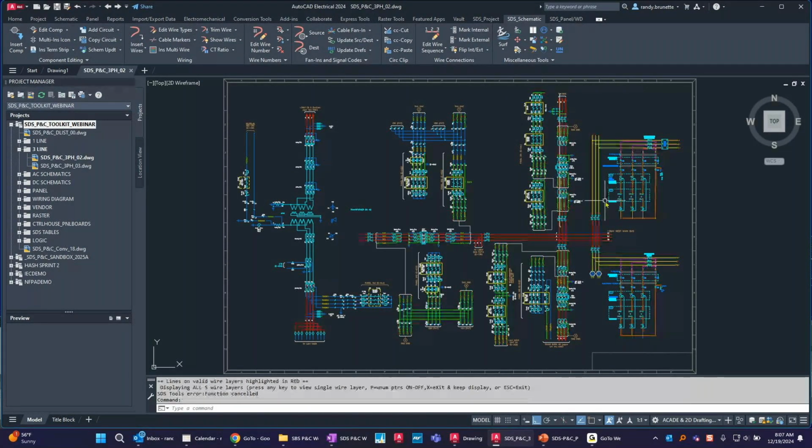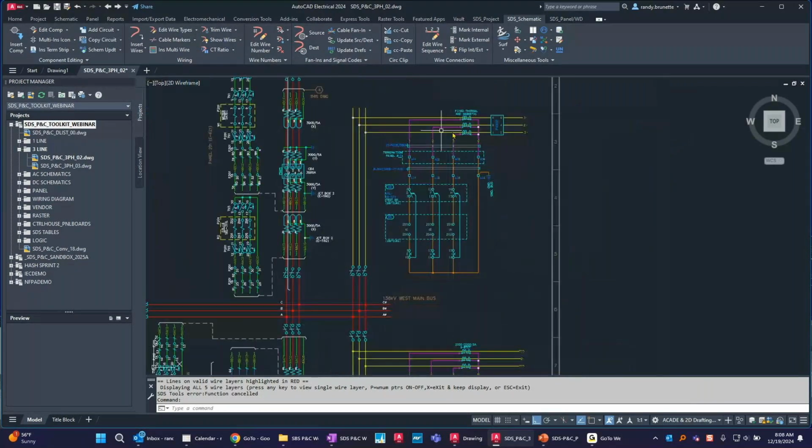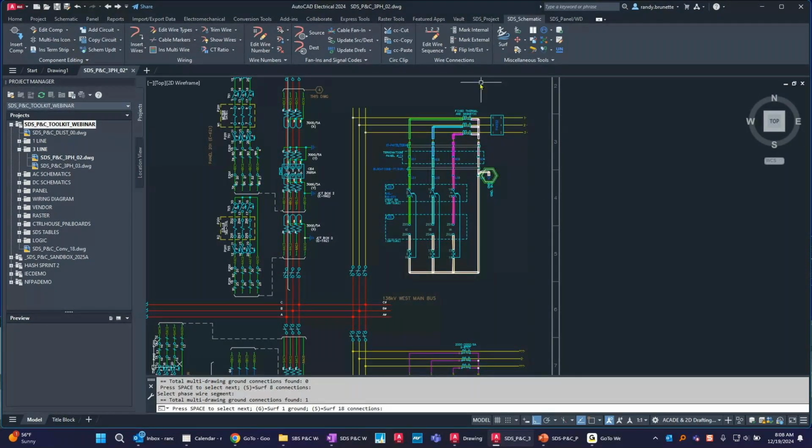We also have a tool that allows you to check or follow the phasing in your drawing. So if I go to that same flyout and pick Show Phase, I can now check or select each one of these wires that are in my phasing, and notice how they're showing up as different colors, and they're tracing the phase all the way from my CT up here down to the protection relay down in this area, passing through various terminals, test switches, and so on.